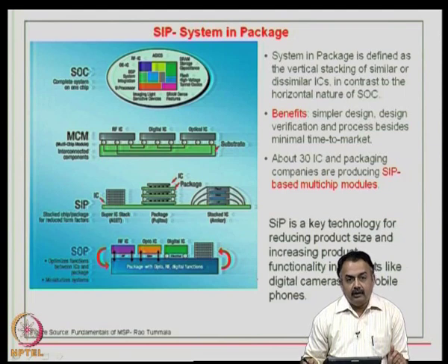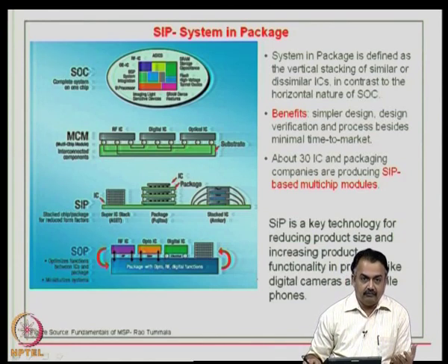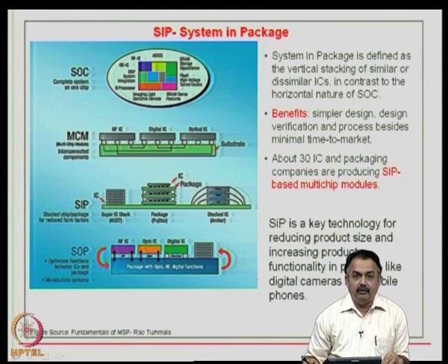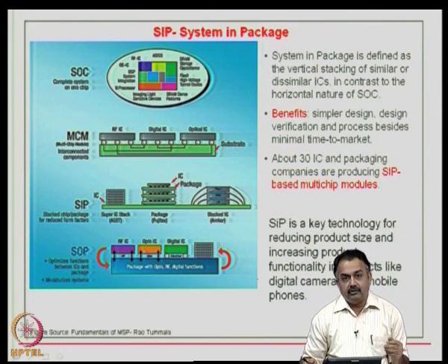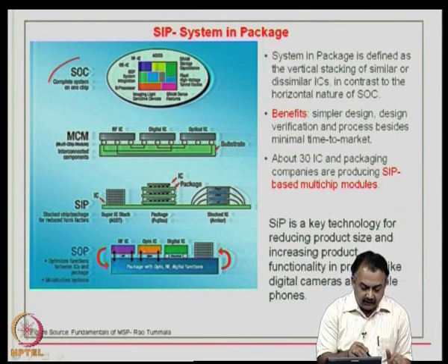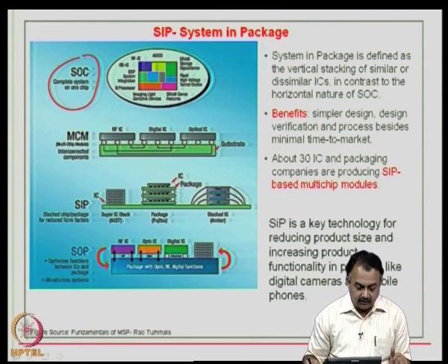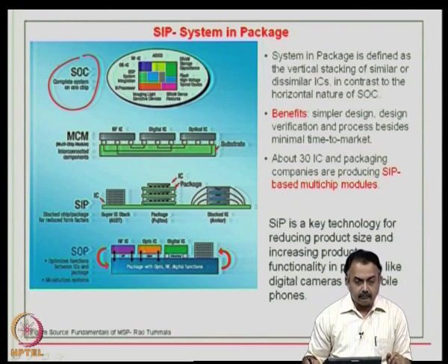We will now look at another package format that is now widely being used, but selectively, known as system in package. System in package is not available off the shelf. It is a concept where you can establish some kind of vertical stacking of similar or dissimilar ICs, in comparison to the horizontal nature of MCM that we have just seen. So, if you look at this figure here, the different definitions, first is what we have seen, SOC, system on a chip. We are trying to build a complete system on a chip.